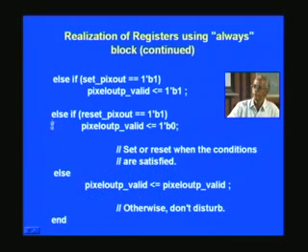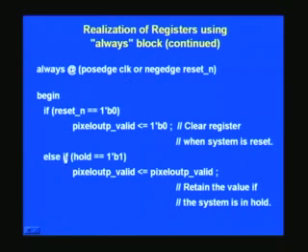Now you have seen the if, else if, and finally else structure. If you just count 1, 2, 3, 4 and 5, from my experience, if you exceed this 5, your speed of operation will get hit. For example, if you are aiming at 100 megahertz operation on an FPGA, let us say field programmable gate arrays.